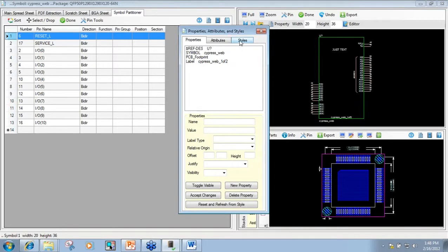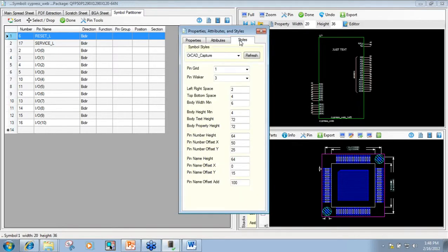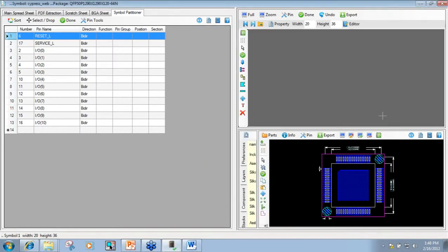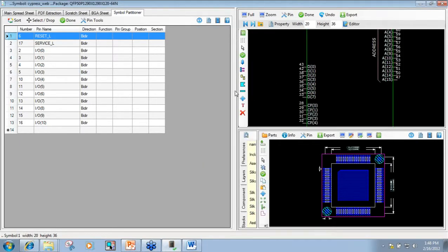You also have the ability to do different configurations for the style. So if you didn't like these long pin styles that you're getting there, we could change what we call whisker to some other size. So in this case, it just shortened those up. If I zoom in here, I just can't do it when I'm in that window. So it just made short pins in that particular instance. So those are some of the configurations that you can do. You can set up text sizes and offset for your text, etc.